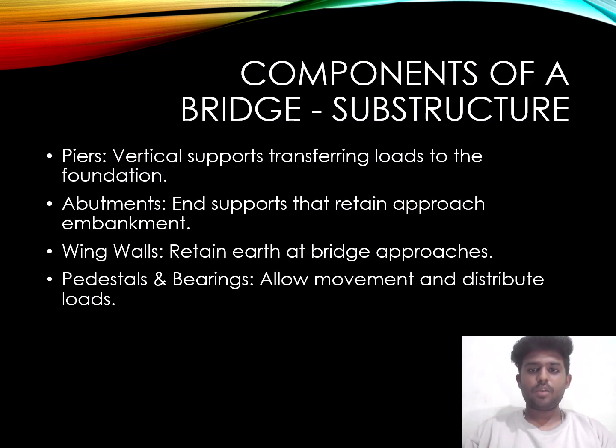Next component of a bridge is the substructure. First, piers, vertical supports transferring load to the foundation. Next, abutments, end supports that retain approach embankments. Wing walls retain earth at bridge approaches. Pedestals and bearings allow movement and distribute loads.